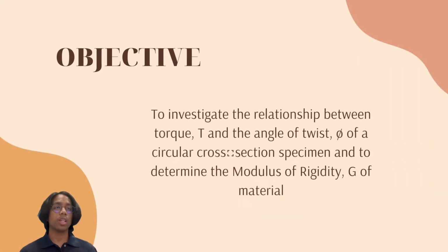Okay, I'm going to explain about our objective. Our objective is to investigate the relationship between torque T and the angle of twist theta of a circular cross-section specimen, and to determine the modulus of rigidity G of materials.